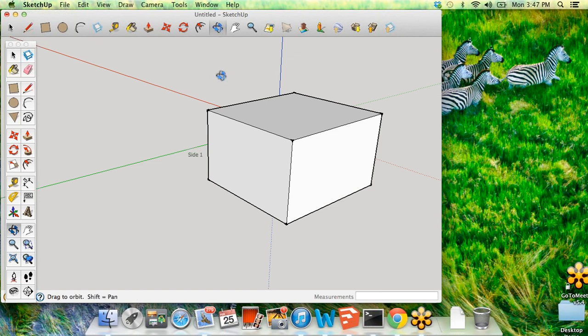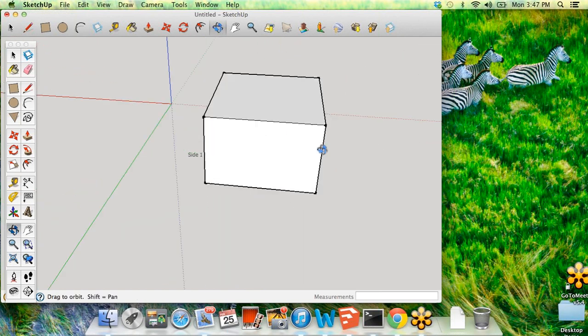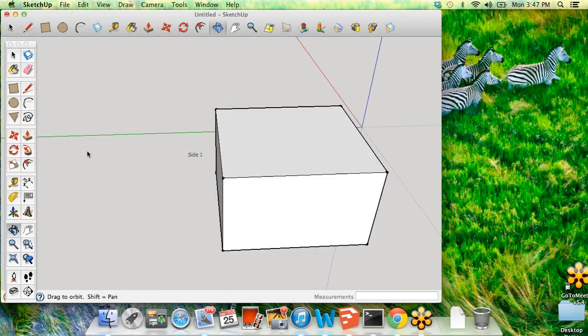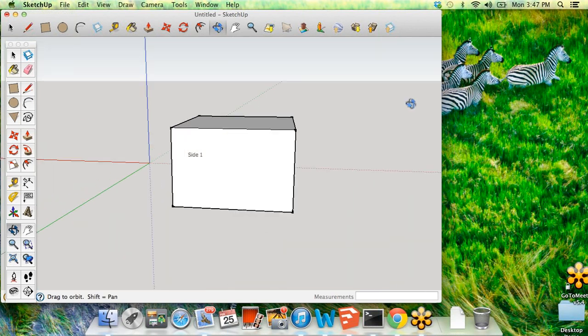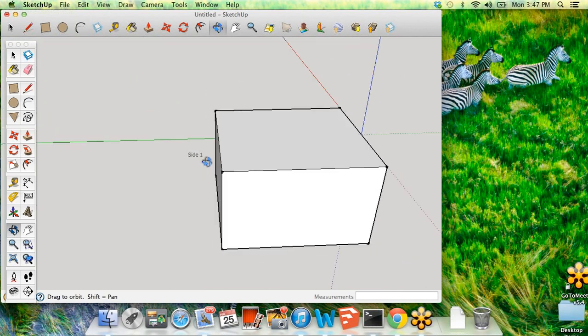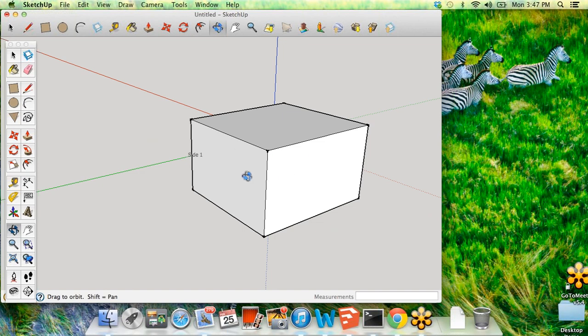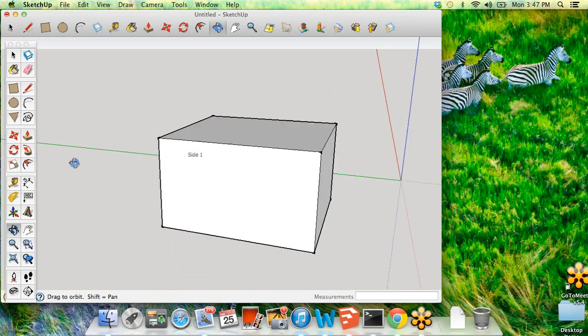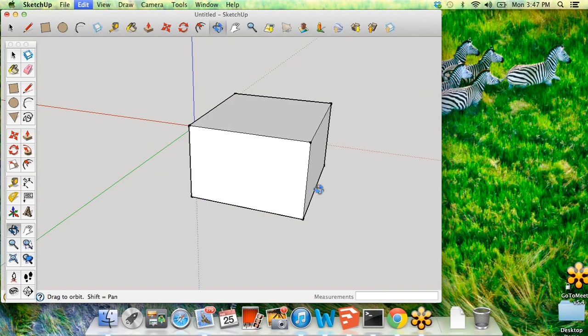If you use the orbit key, you'll notice that this first text that we entered doesn't act like the other shapes and lines that we have been using. It's fixed to the screen at that point as opposed to being fixed to the object. I did edit undo to get rid of that text. That free-floating text might be nice if you wanted to enter a title, such as my box.